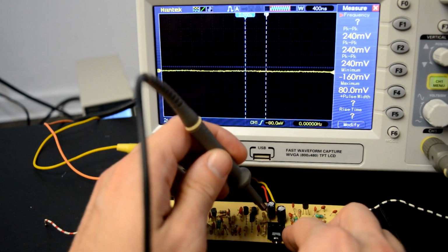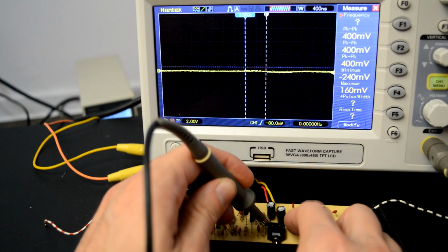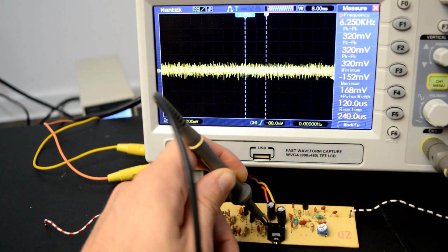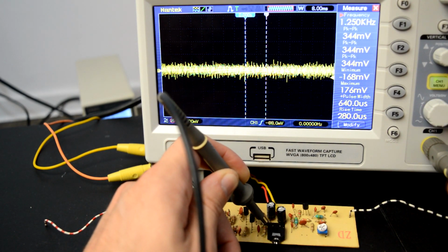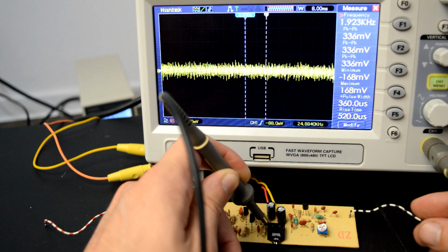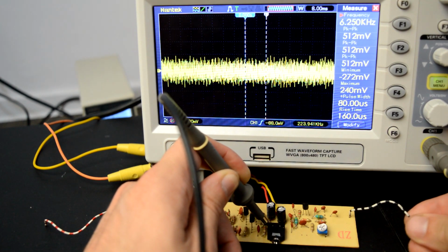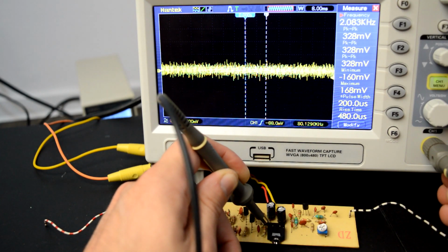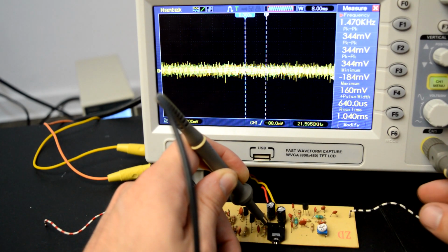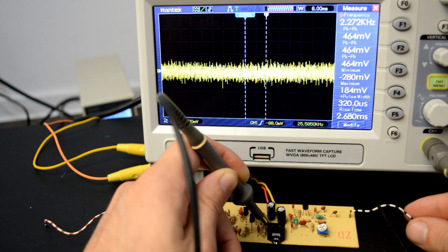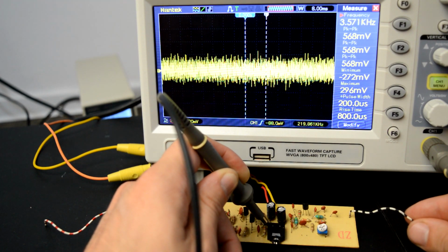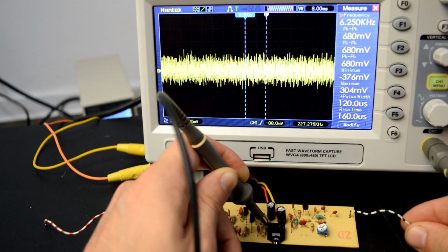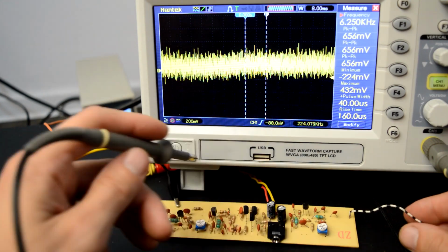So finally, we can look at what comes out of the voltage controlled amplifier. Again, we see only noise, but when I bring my hand closer to the volume antenna, we can see that this noise is increasing. So even though it's not very obvious, the volume control is actually working. By bringing my hand closer to it, I'm increasing the gain of the amplifier.